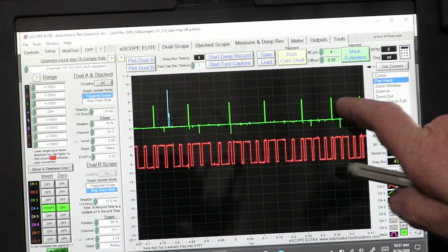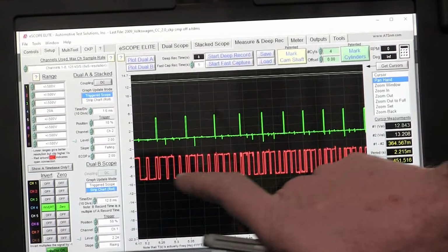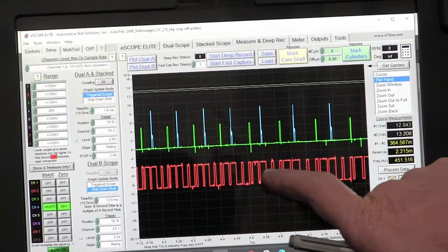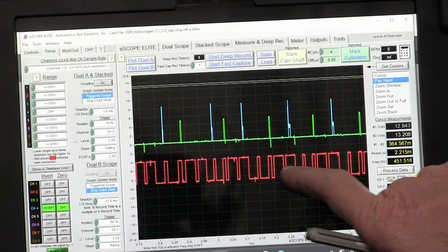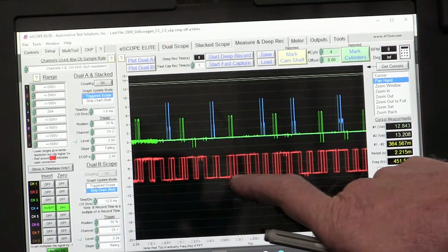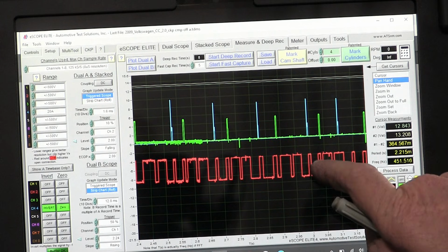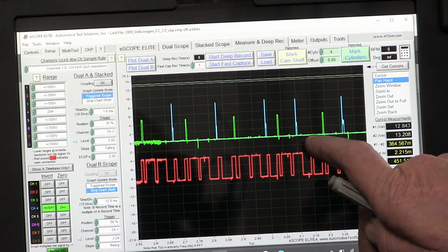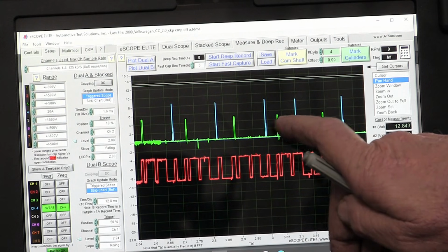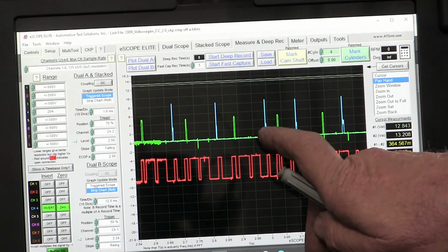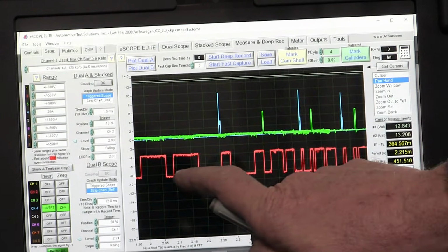And here we've lost the injector totally. The injector has stopped firing here. So right away, the computer has some timing issues that we can see just by looking at some basic waveforms, as we can see here. And we can see that the injector was firing closer to being right here. See how close we are to the green, and see how we're way away from the green right here? A fire cycle is from ignition to ignition. This is in a different position than this. That's changing because the computer must be confused on the inputs.